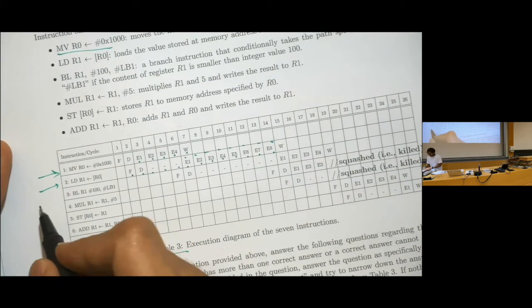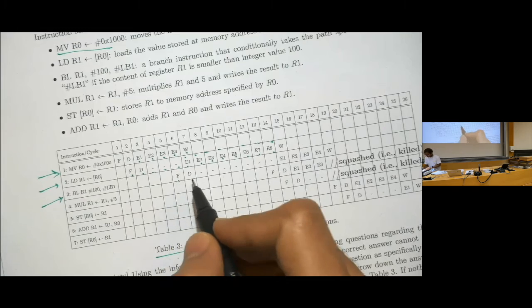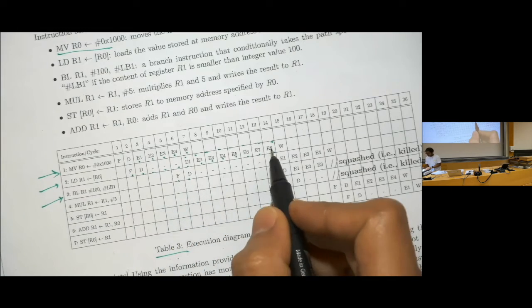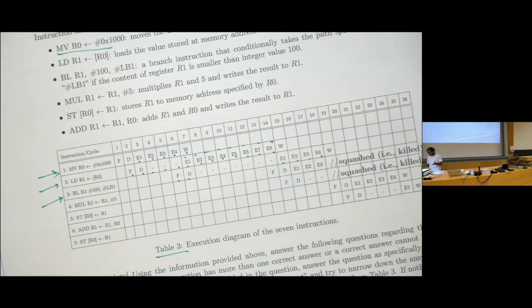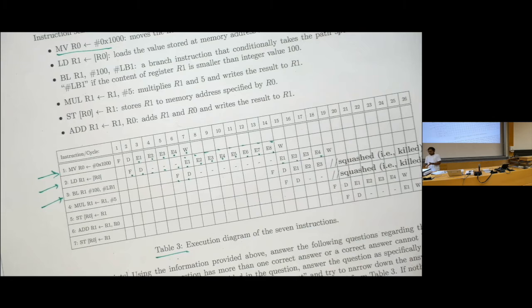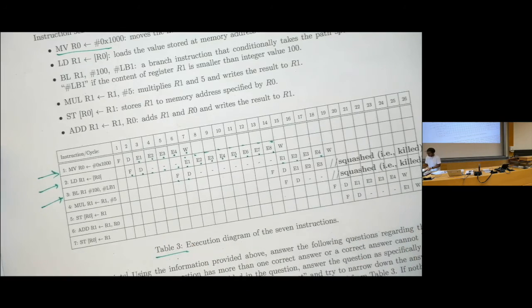All right, up next we have branch if less than R1. I see that it does fetch, decode. It is waiting until the execution stage gets freed, and then it does E1, E2, E3, E4. That sounds good. That means that I could not schedule it immediately, but there were no load stores in this. Perfect. Up next, I see this very interesting data point called squashed.